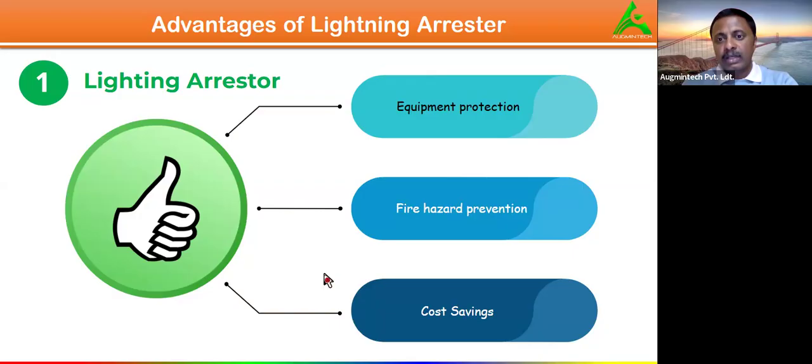And one more thing, if you have a nearby building taller than our building, and they have installed one, it's not an issue if we have not installed it. Why? Because lightning strikes are going to strike at the highest point only. That's the basic thing actually.